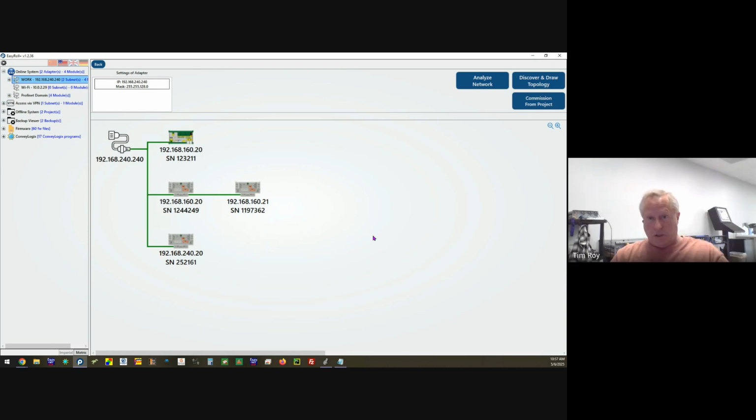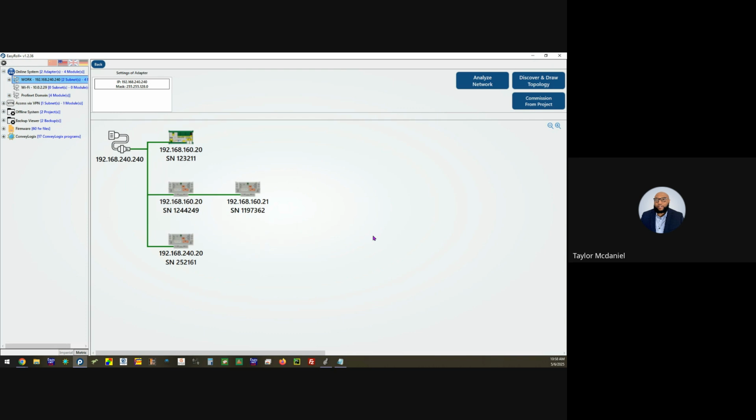First, the card will determine, can I be node 1? And it does that by looking at the Ethernet ports. Do I have a connection on my left port? Yes. Do I have a connection on my right port? Yes. Well, that means I'm in the middle and I can't be node 1. Abort procedure.